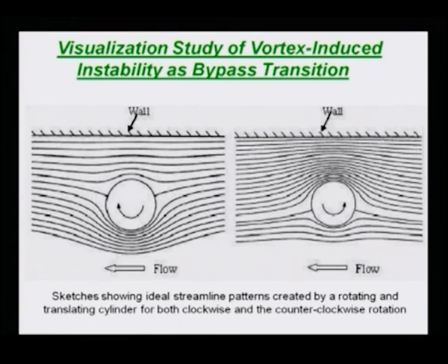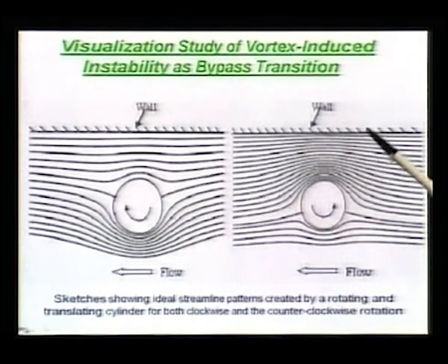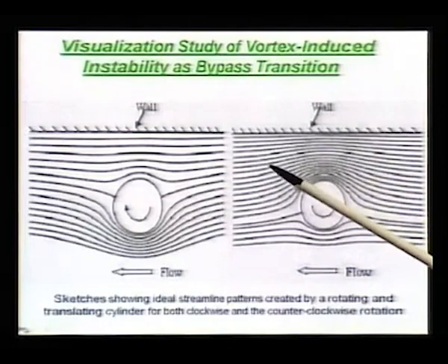So, again to emphasize the point, you see what happens. The boundary layer stability or instability is dictated upon the impressed pressure gradient from the outside. So, in this case, what is happening? So, your shear layer may be here embedded right next to the wall, but what is the pressure gradient that is imposed?